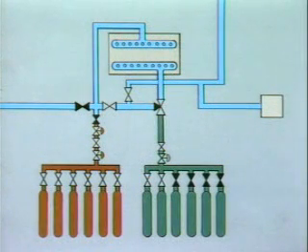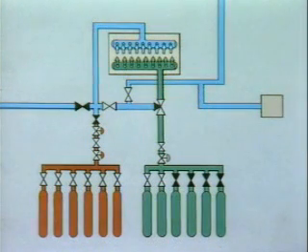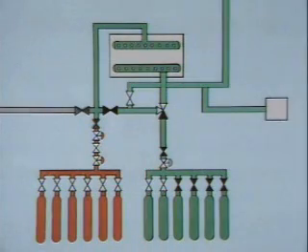When maintenance is complete, the purging process is reversed. First, the generator is sealed and pressurized with air for a leak test. Then CO2 is used to force the air out of the generator. Finally, the CO2 is replaced with hydrogen.